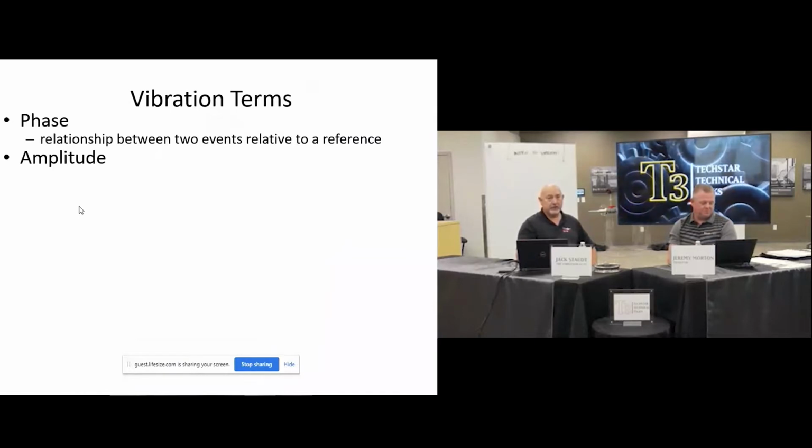And you can measure this with the right analyzer, data collector. There are so many of them out on the market. You have two ways you can do it. You can use what's called absolute phase analysis, where you use a transducer and a tachometer, and then you can do two-channel relative phase analysis, where you use one channel as your reference and the other channel as your movable.